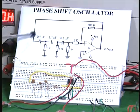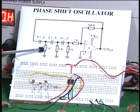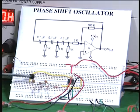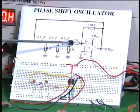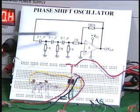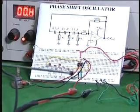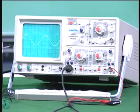That output I take and give it to a series of 3 RC sections. They are all equal values, 0.1 microfarad and 1K. You can see in the circuit here 3 1K resistors and 3 0.1 microfarad capacitors, and that output is connected to the input pin number 2 of the operational amplifier that you see here. For the feedback resistor, I have used a potentiometer, a carbon resistor here, and the output is monitored using the oscilloscope.